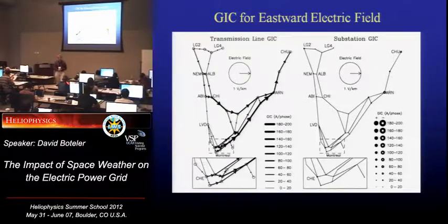Has there been any evidence of a significant GIC effect from isolated substorms, ones that aren't directly part of a storm? Not that I know of. My experience has been that you do get them, but they tend to be smaller. So it's really the biggest substorms that cause the problems, and those only occur during a major event, like the '89 event. But we can very closely tie it to an actual substorm. It's not the main phase doing anything, it's the actual substorm.